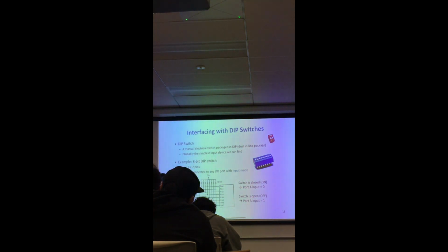So disconnected, connected. Okay, so the switch. Assume that the slider is red, right? So if I put it here, this means it's disconnected. What voltage will be present as the input of this microcontroller if this is disconnected? Maybe 3.3. Well, whatever VCC.